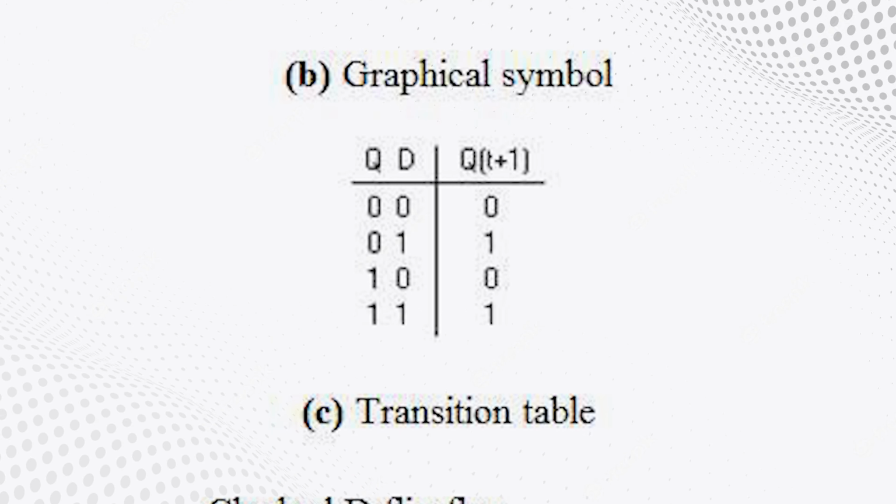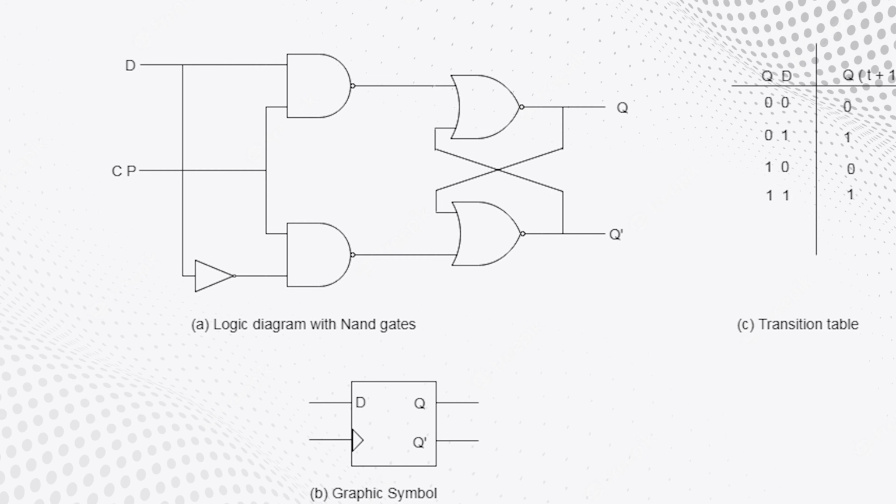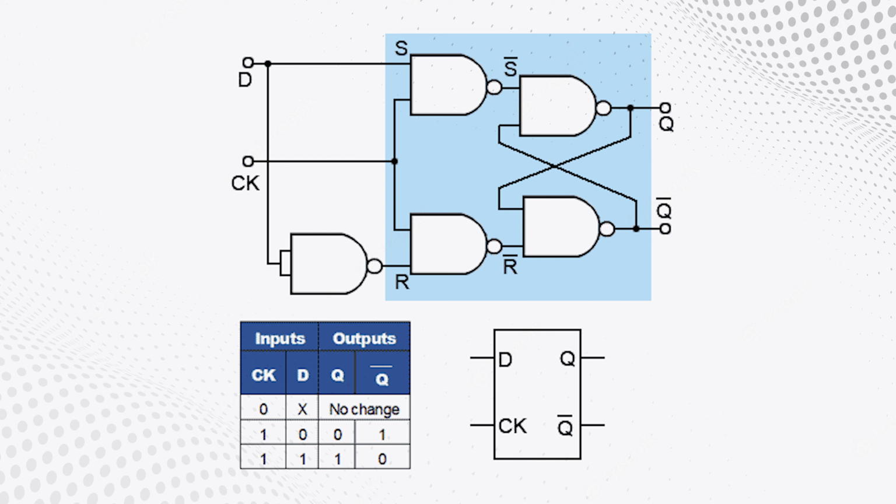Operation of flip-flops in computers and other digital devices must be synchronized with the help of clock pulses. Therefore, flip-flops are constructed with clock enabling circuits using AND gates. In positive level clocked flip-flops, the outputs are enabled during the high state of the clock pulse, and in negative level clocked circuits, the flip-flops are enabled during the low state of the clock pulse.